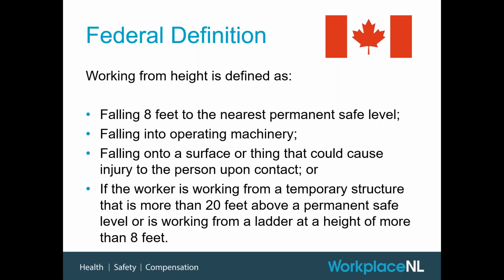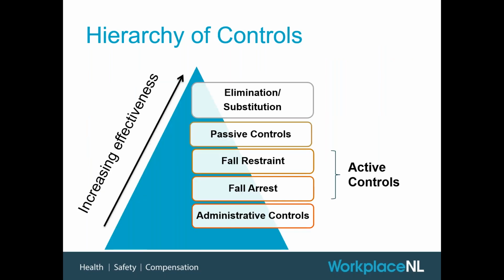If a worker is working from a temporary structure, so that could be a ladder, a scaffold, that is more than 20 feet above the next safe level. Sorry, a temporary structure such as a scaffold, then they need to, or if they're working from a ladder at a height of more than 8 feet. Sorry, I apologize for that, a bit confusing there. So again, there's some nuance to the rules depending on what jurisdiction you're working under.